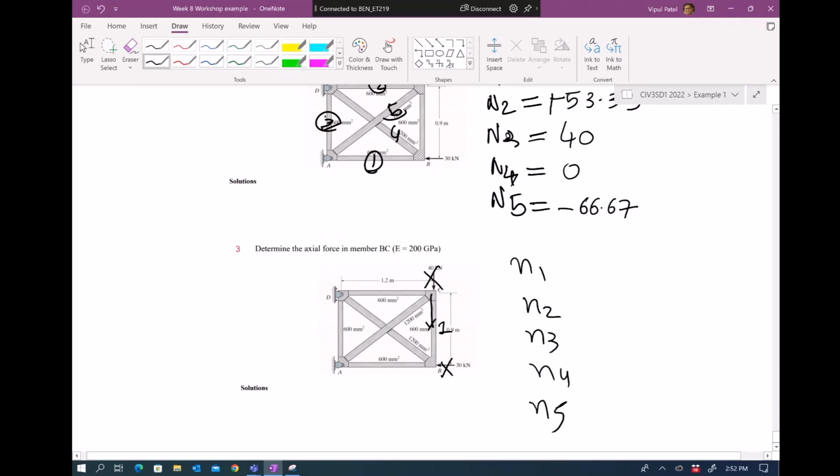That is given here. Sorry. Which one? The arrow? That is in the next one. Okay, the redundant force. And we find N1, N2, N3, and N4 reaction force and joint methods. Right, and that's how we can find the deflection delta CB, from C to B. Deflection delta CB would be the sum of capital N, small n, L over E A, for the 5 members. You substitute that value.